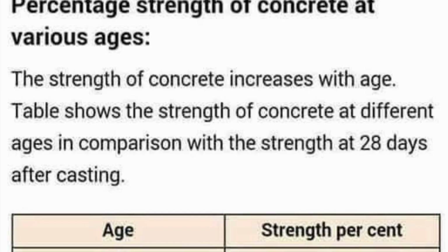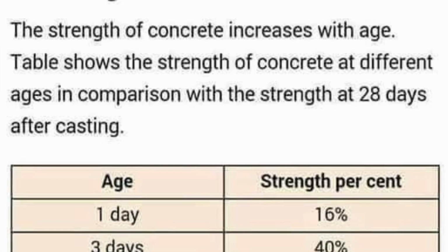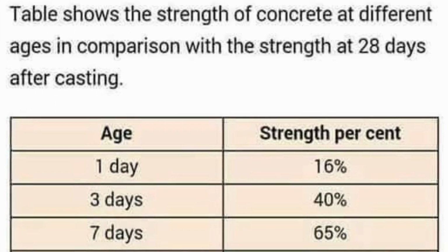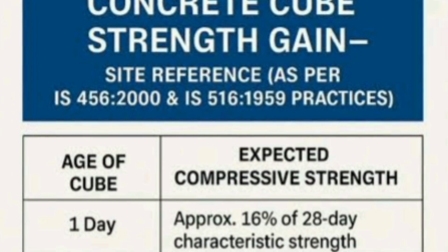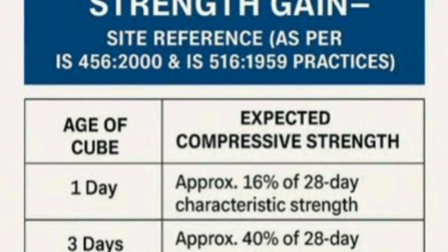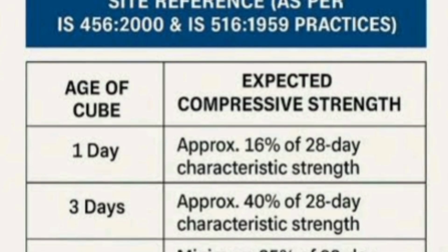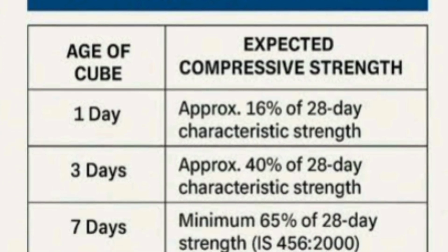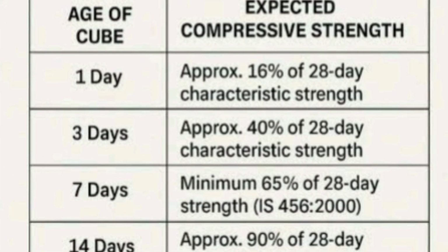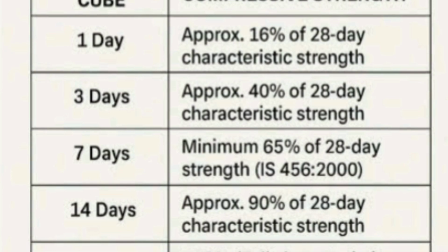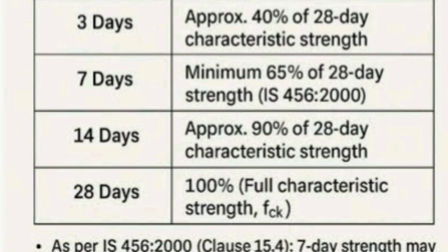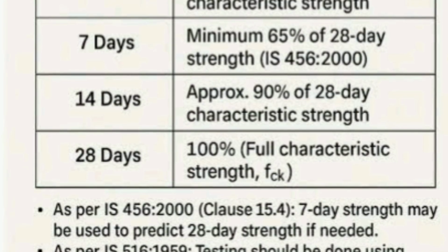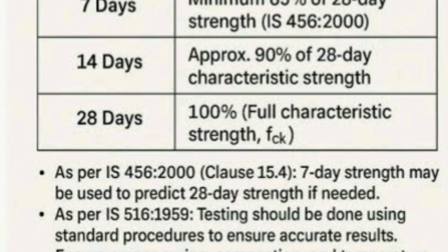The duration of curing is also critical. While concrete gains most of its strength in the first 28 days, hydration continues for months and even years. Stopping curing after just 3 or 4 days is a common mistake that sacrifices significant long-term strength and durability. For high-performance concrete, wet curing for at least 7 days is a minimum, and for concrete with supplementary cementitious materials like fly ash or slag, longer curing is essential as they hydrate more slowly.